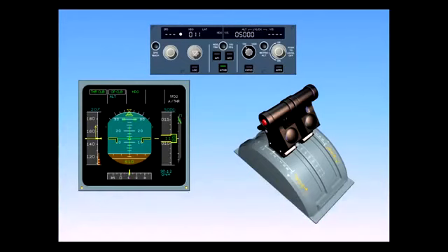In normal operation, when the autothrottle is on, the levers are left in the climb detent throughout the flight until the flare. The autothrottle adjusts the thrust as required between idle and max climb. Note that the thrust levers do not move even though the thrust changes. Should the pilot need additional thrust, he may at any time push the thrust levers forward and manually control the thrust.